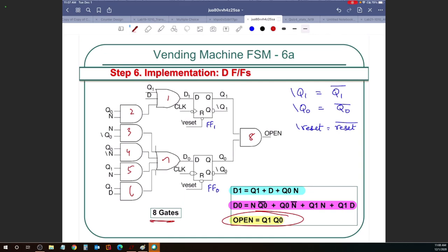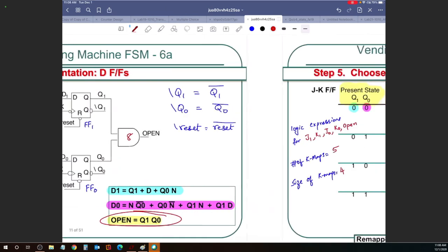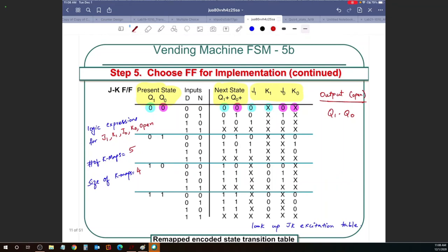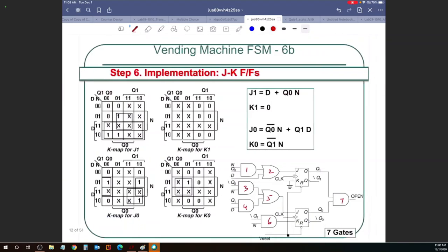However, in general, if you had to choose a flip-flop without knowing the cost, then the JK flip-flop suits most applications the best. So in general, JK flip-flop for ease of use, for registers you would use the data flip-flop, D flip-flop, and for counters you would use the toggle flip-flop. That's a summary of how you would go about choosing the flip-flops. All right, so we have taken a look at that.